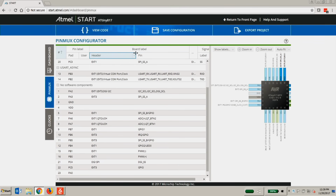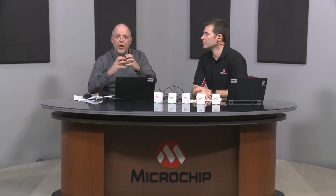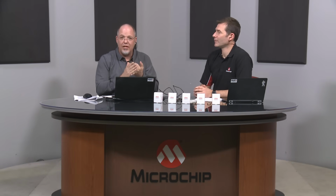One of the things that I didn't mention when we added the UART is that, because we selected the ATtiny817 Xplained Pro board at the beginning, our UART automatically got mapped to certain pins. These pins, as Jacob mentioned, are going to communicate with the EDBG circuitry, and that's going to convert our UART signal into a USB signal that we're going to visualize later inside Studio.